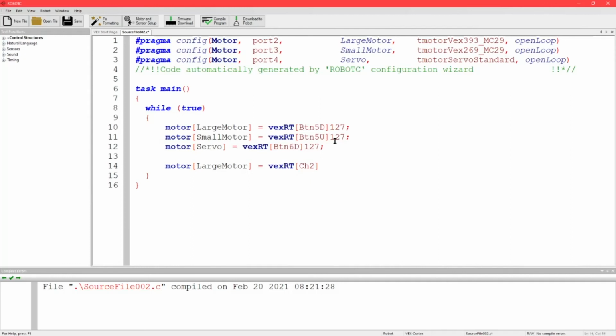And so you'll just do that, and automatically the max output you can get from the joysticks is 127, so you actually don't need to do anything to this, which is really nice. So you will get negative to positive 127, and that's exactly what the motors take in. You can also do this with servos, which is kind of nice.